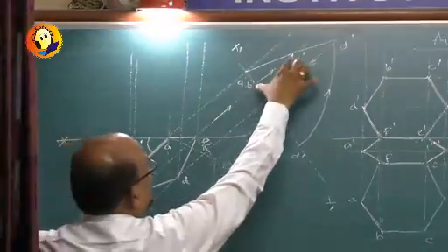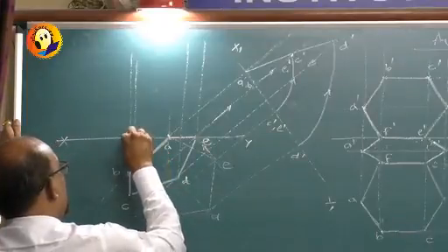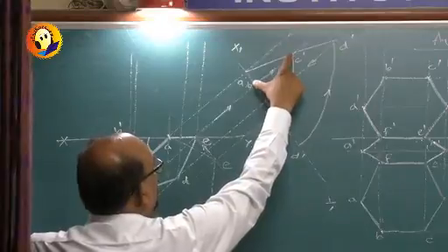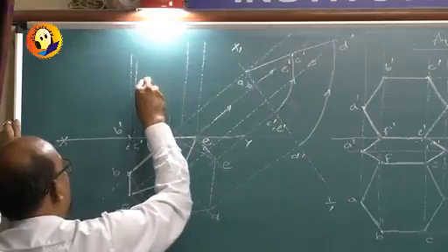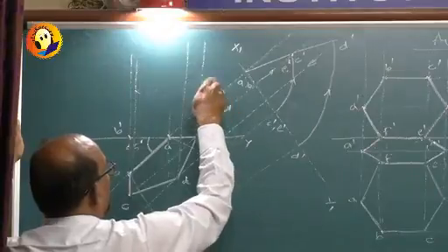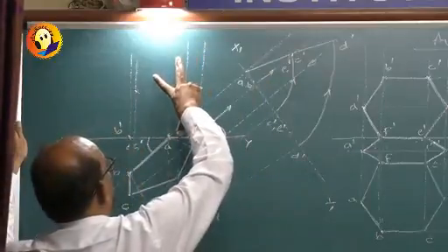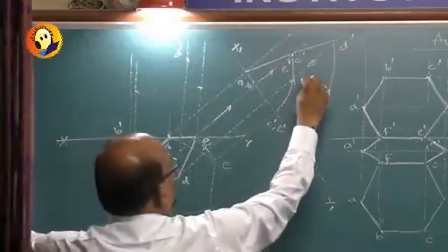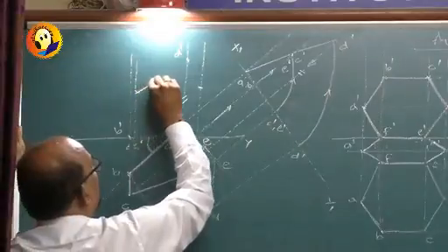And take the distances from this XY. So A dash B dash are here. So this will be A dash and this will be B dash. For C dash and E dash, this is the distance from XY. So take that distance from C, from XY, mark it. So this is C dash and this is going to be E dash. Whereas this much is the distance of point D dash. So this distance I have taken and marked from this XY. And then if you join them,